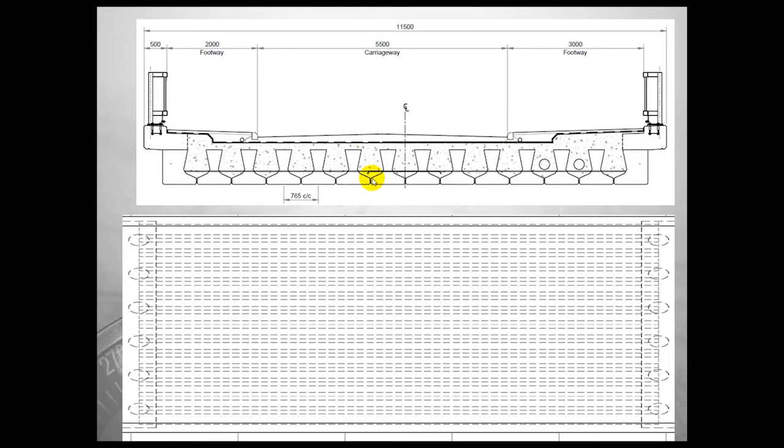general type of section. So these type of sections we will bring in from AutoCAD, but in terms of applying tendons and other properties, you can very easily use the automatic feature of the software to generate tendons for those sections which have the slab at the top. So we'll create such sections first which have the slab at the top, and then we will bring in sections which are basically infill type, with the slab actually filled in between the gaps of the equally spaced precast girders.